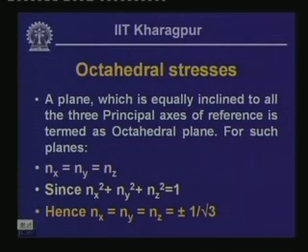The octahedral stresses are nothing but the stresses which act on the octahedral planes. So, we will have to know what we really mean by octahedral planes. The octahedral plane is a plane which is equally inclined to all the three principal axes of reference. This is generally termed as octahedral plane.